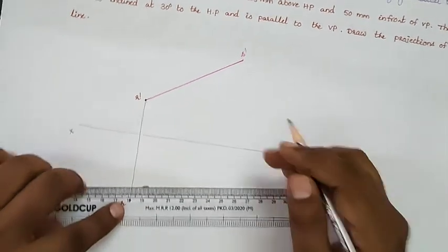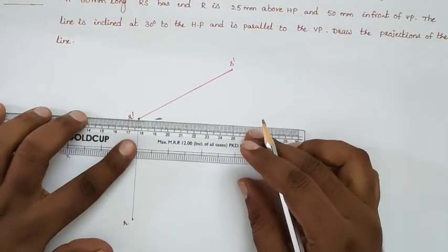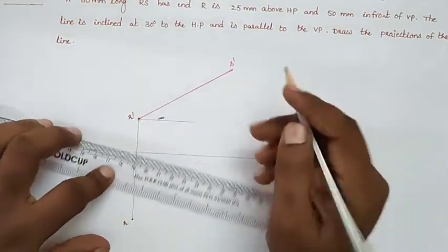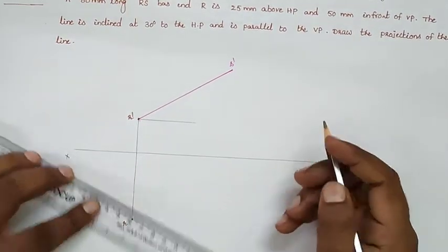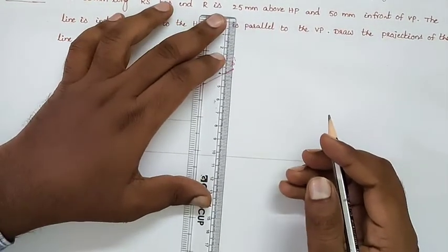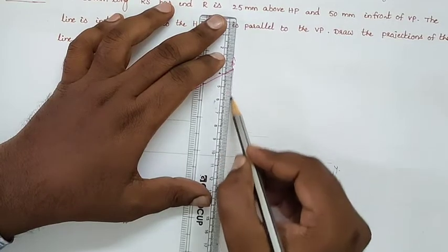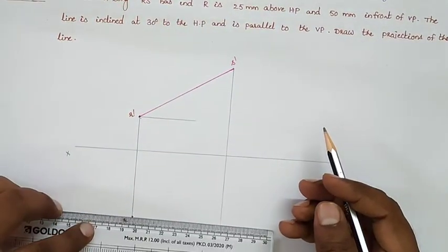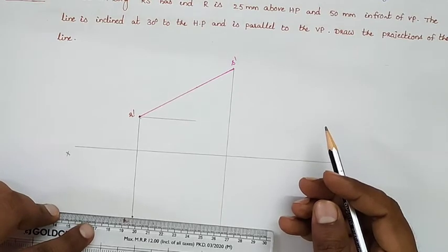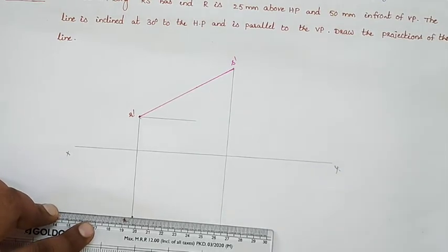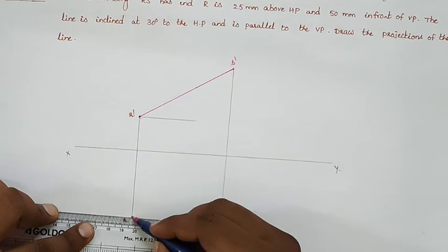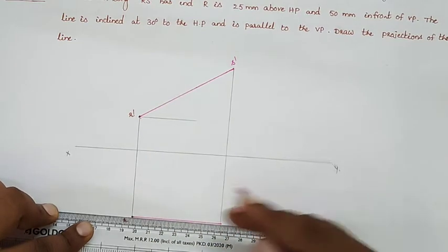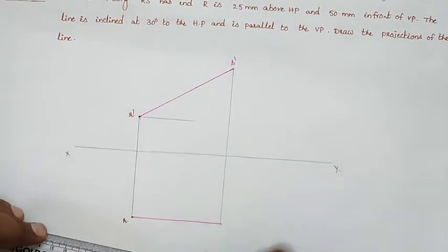And also I am representing this angle. So from S dash, suppose you draw a projection line, and from R we draw a horizontal line, we will get a line which is parallel to the XY, but it is a projected length, less than the true length.